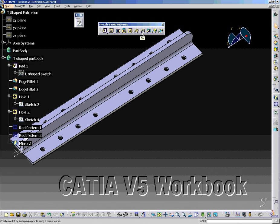along. The Slot tool creates a slot by sweeping a profile along a center curve. The profile does not have to be a closed profile. The center curve can be an existing entity. The profile is subtracted from the intersecting or existing solid.